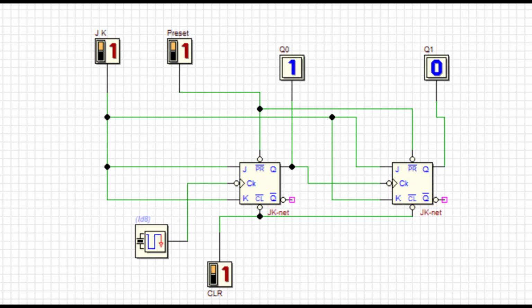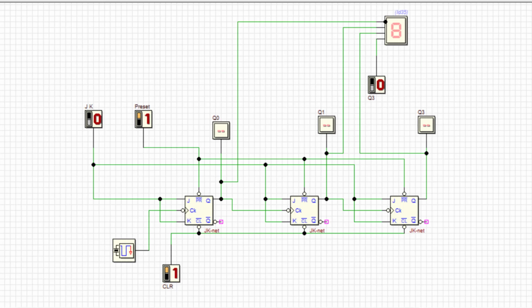Similarly, when you go to the 3-bit counting, let's clear the flip flop outputs. Let's make J equals 1 and K equals 1. Now it's going to count from 0 to 7. 1, then 2, 3. So this is also negative edge triggered. Everything is the same. The only thing is I changed Q bar to Q as a clock to the next flip flop. This is for 3-bit.